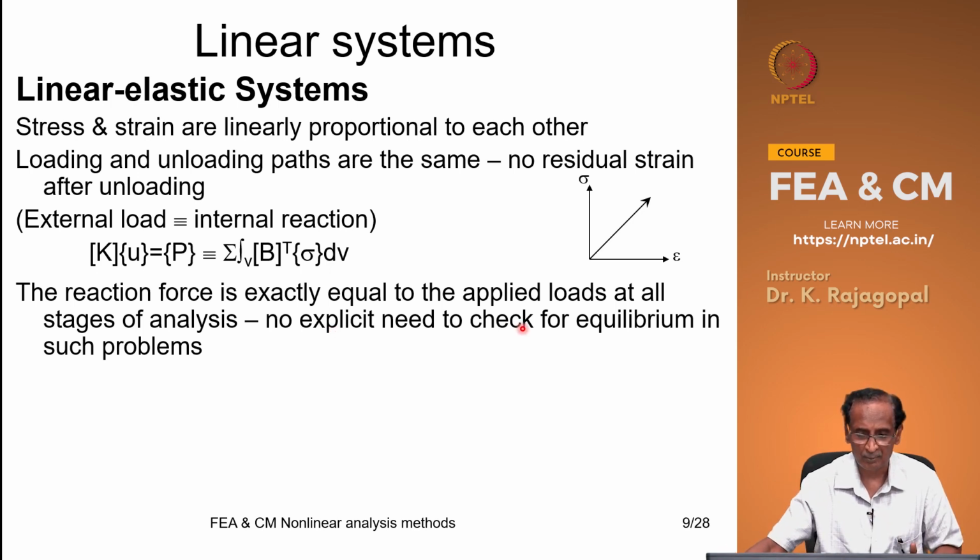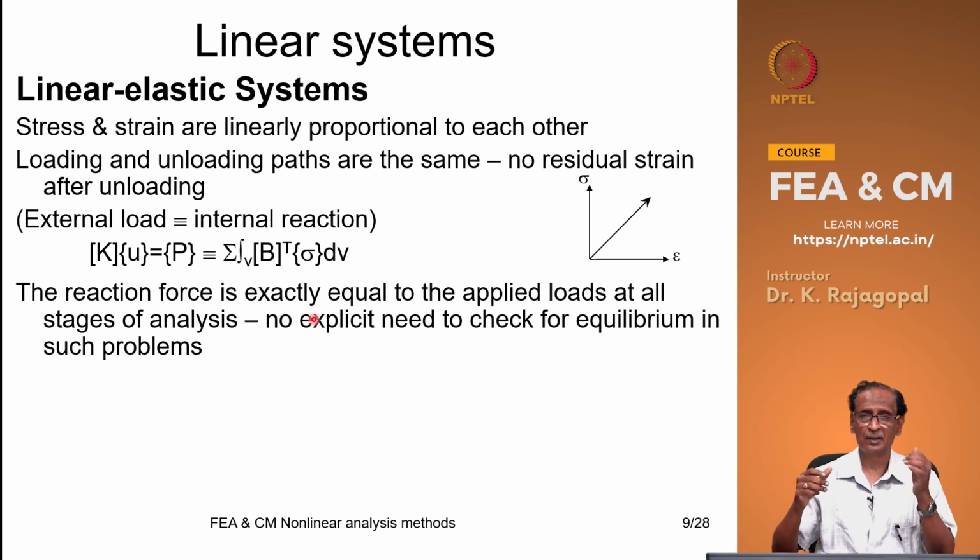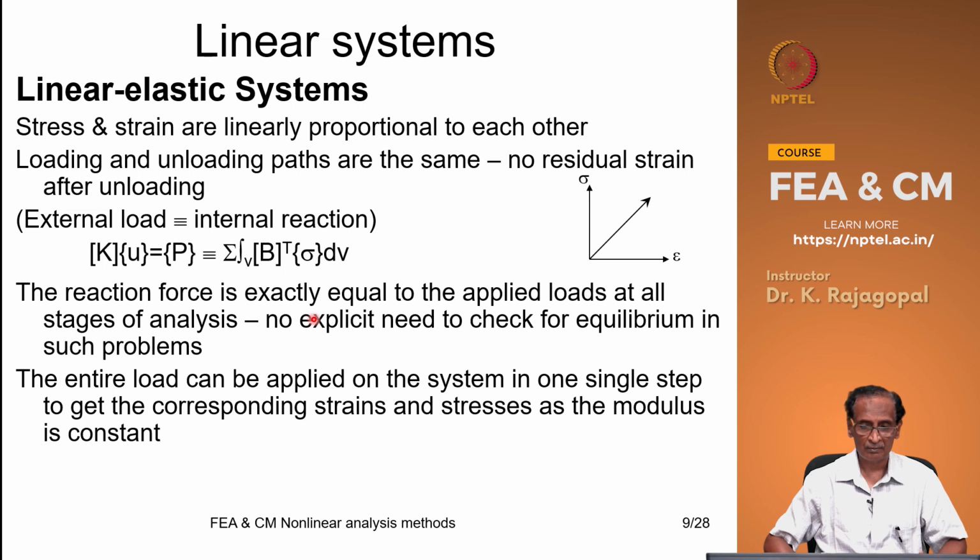So, we do not normally check for equilibrium in such problem, but even if you do check for the equilibrium, you will see that your out of balance force is very small, and the entire load can be applied in the system in one single go, and we can calculate our stresses and strains as the modulus is constant.